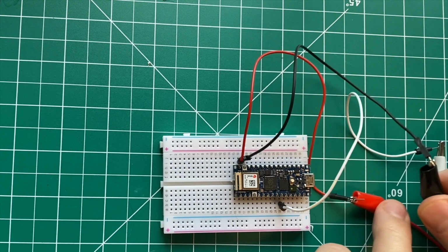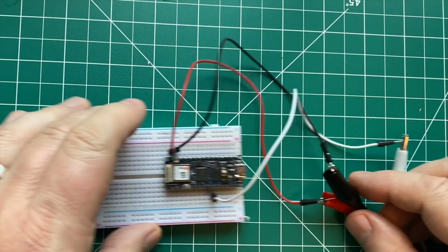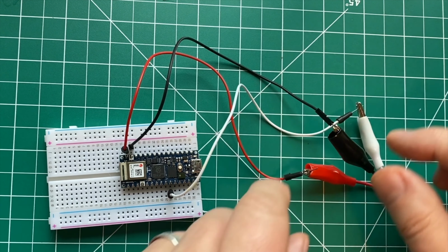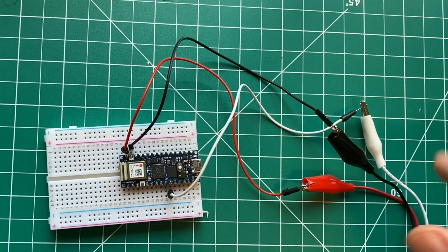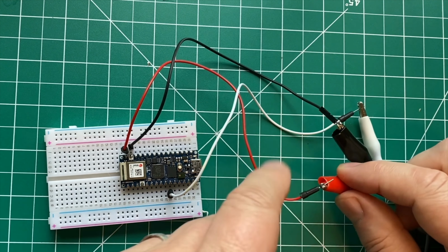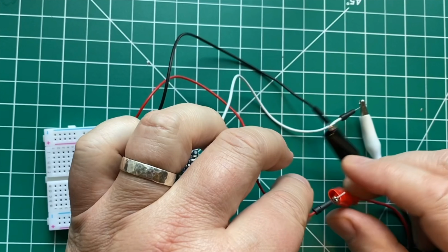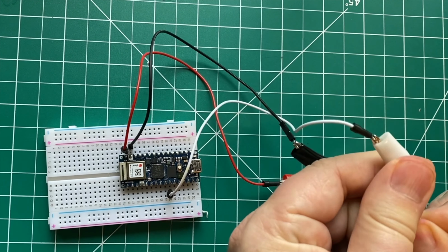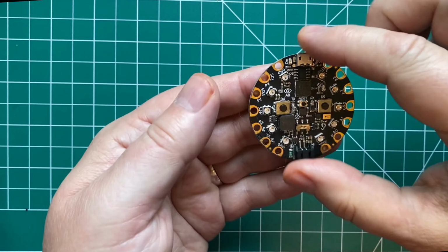Now in my connection here, my alligator clips have exposed metal, and it's possible that I might accidentally bump the wires and cause a short. You can probably just spread these wires apart so that they don't touch, as long as you don't move your project around, but if you're uncoordinated like I am, you can always wrap the ends of the wires in tape if you need to. The covers on the ends of alligator clips can also help keep the metal parts from touching.